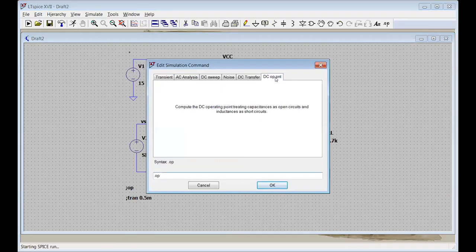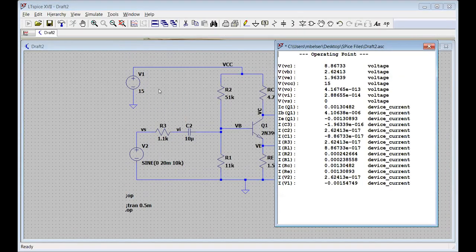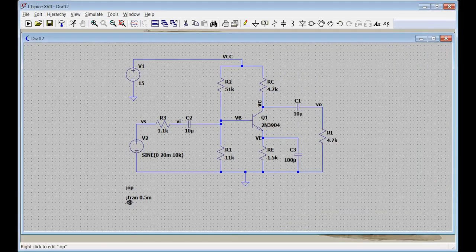Okay. And then we're going to do a run. Hold on. Okay. And so now it should give me the same DC values that it gave me before. So it has more nodes now. Say for example, here's my VC. Okay, I found out what was wrong with it. I had 2 resistors named the same thing in 2 different places. Okay, yeah, because they'll think that, that'll do it.